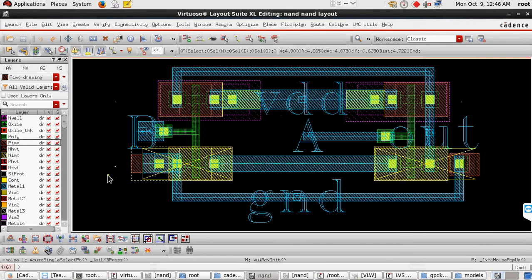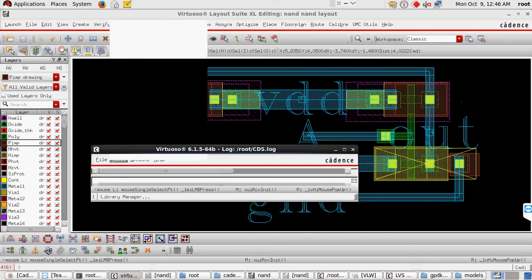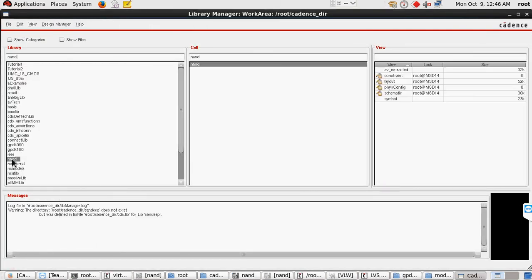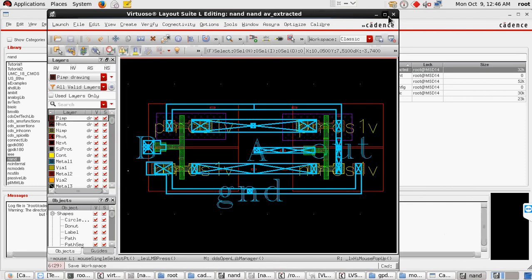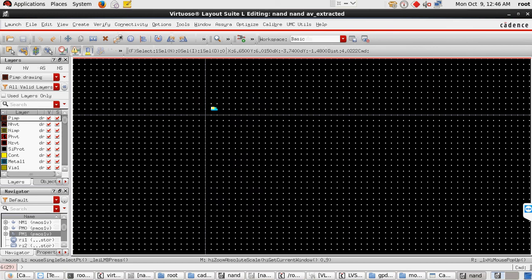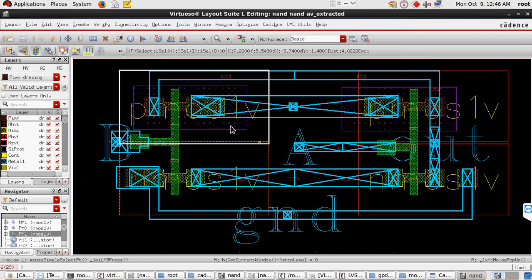So completion of everything. If you want to know what the layout is, just go to here, go to NAND. This one here, the LVS structure is created, so just click on it to appear this one, fit. And here if you want to show classical view, basic view, your choice. Okay, just zoom it, shift F, so it shows the devices also. Okay, this one is control E, control F, it shows the name only, and zoom it.